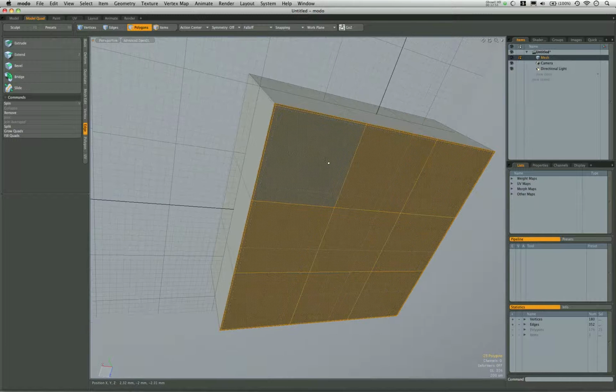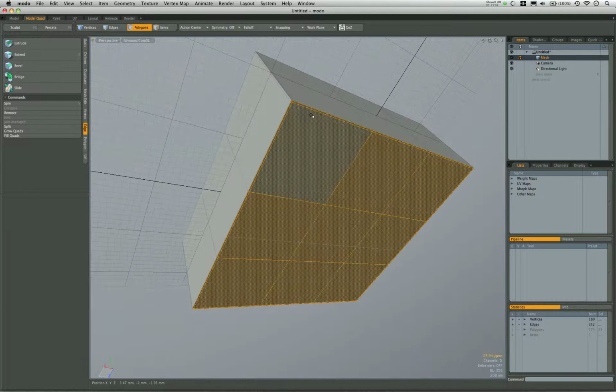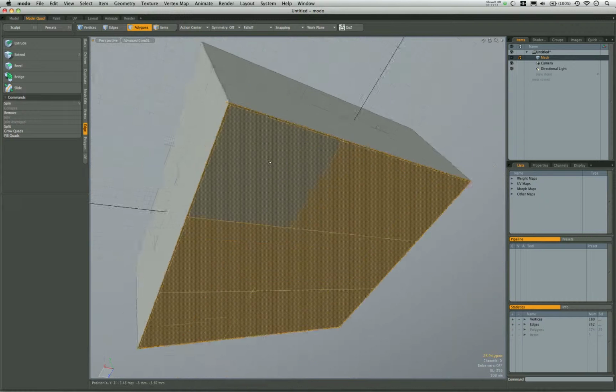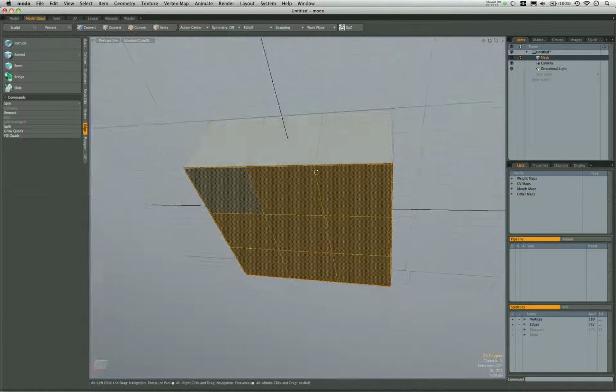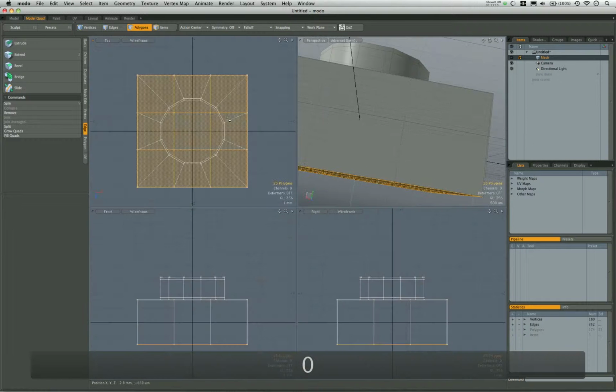If we don't include that outside rim, we can bevel in and we can make these edges as straight as we want, add as many radial loop slices as we want. They're not going to get sharp on the corners. And if we include these crossing edges there, it's still going to give us an edge to define the actual physical edge, and then 2 edges to give us some sharpening of those edges and make sure that they stay a relatively sharp surface.